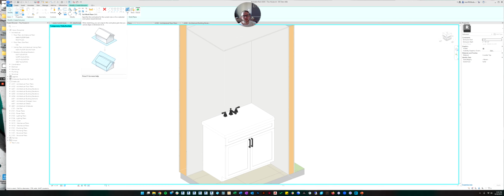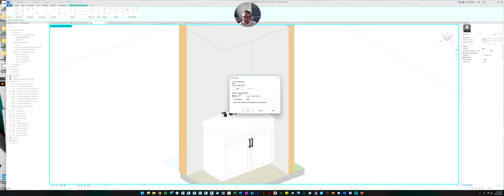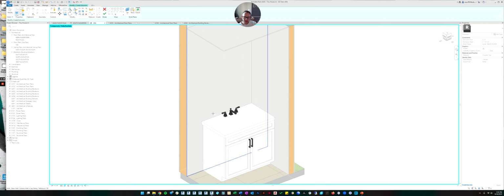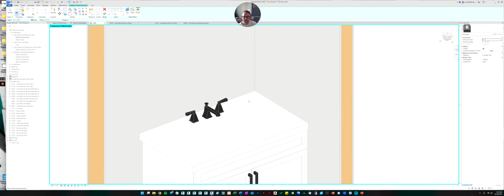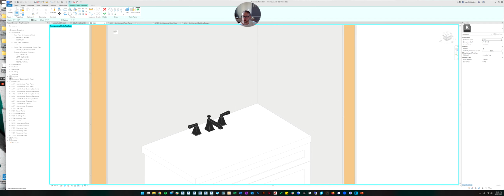If this is confusing to you, you can skip this and just extrude the backsplash the same way I showed you to extrude the countertop. Otherwise, just hit this set button and it brings up this dialog box, and just click this that says pick work plane. And then you're going to pick what surface you want to draw on. So we want to draw on the countertop. So now it's set the drawing plane on the top of the counter.